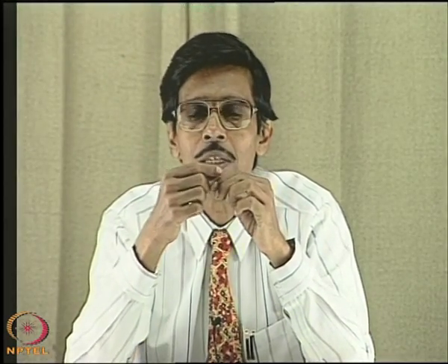Well, but for floating bodies, the beauty is that when the body is given an angular tilt to check its stability, so that it can come back to its original position or not, the center of buoyancy also changes, because some part of the body comes up from the free surface and some part goes down, is immersed. So even in the case where G is above B, there is a chance for the body to be in stable equilibrium, which is decided by another point known as the metacenter.